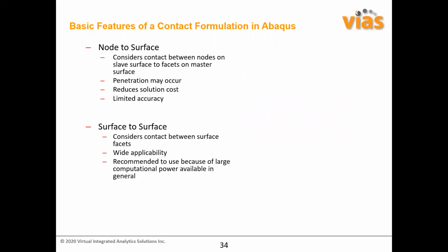Computationally, that is efficient. But the problem is that penetration between the surfaces may occur. It does reduce the solution cost, but it has limited accuracy. Now, with the advent of high-speed computers and the high-power computers that we have, there's a better algorithm which considers the contact between surface facets directly.